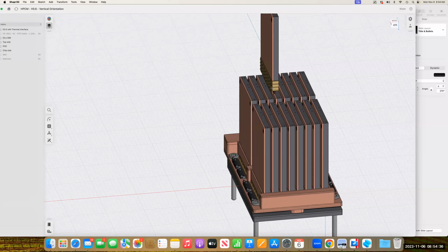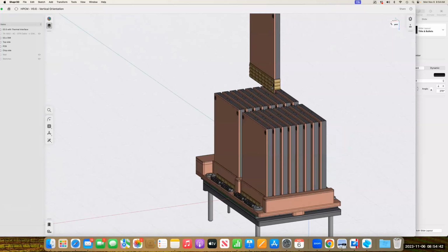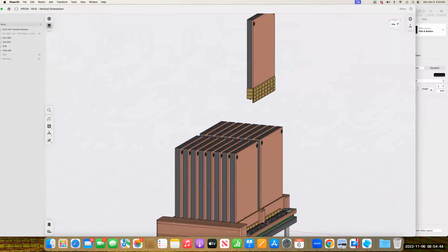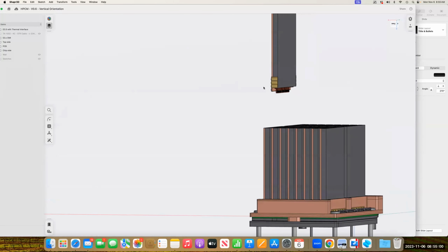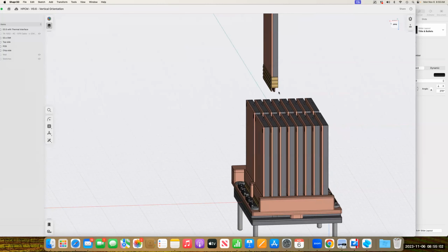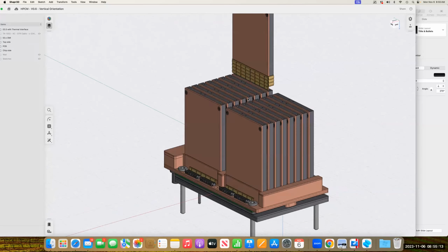But we do have a thermal interface here, which is somewhat spring loaded. Now, I've only got it on the 3 sides. Whether we can actually squeeze in and put some on the back as well, that would give you some sort of natural compliance alignment with the compression of those thermal interconnects, and that could be before the electrical interconnect actually starts as well. So does that make any sense, or does that enhance the possibilities of what we can do?